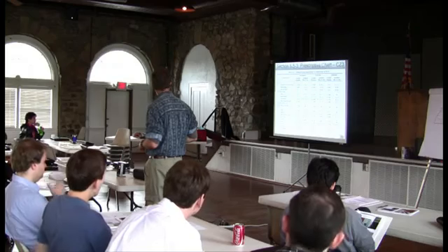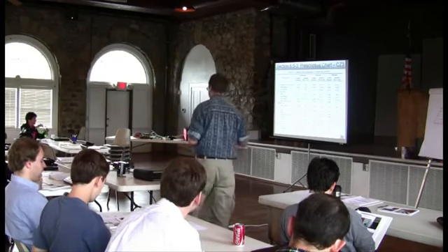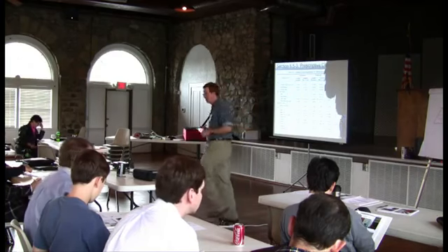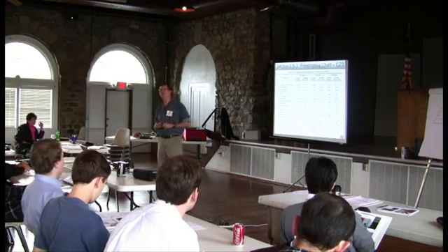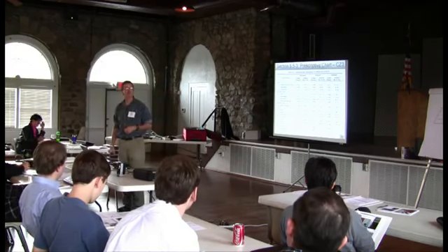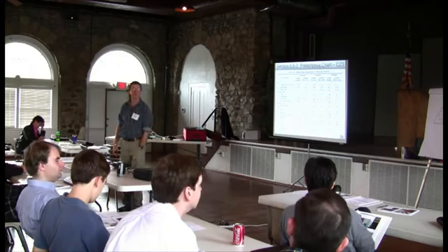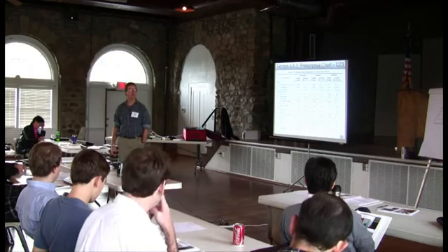All right. Does anybody have any other questions on roof insulation? We'll review those in a second. Okay, walls, Brandon. R38, that's 12 inches? R38 of, for example, fiberglass, R30 is probably about 12 inches. So you're looking at more than 12 inches of loose fill fiberglass. You might be able to do it in a batt that's R38, but